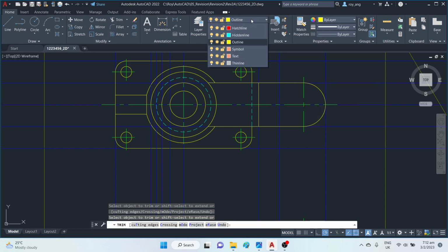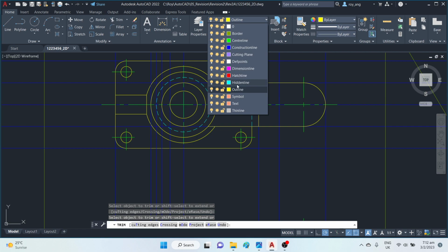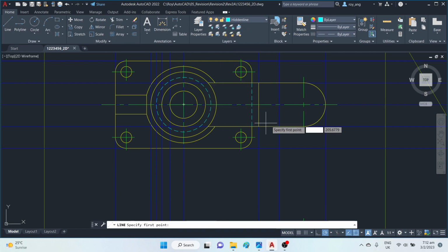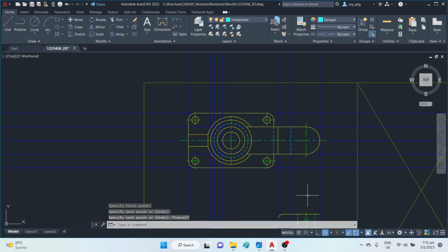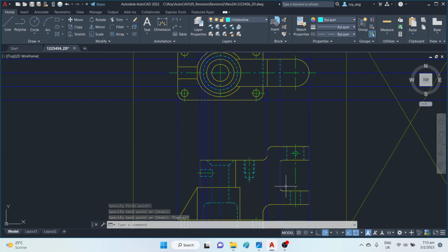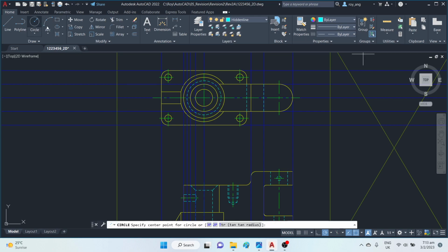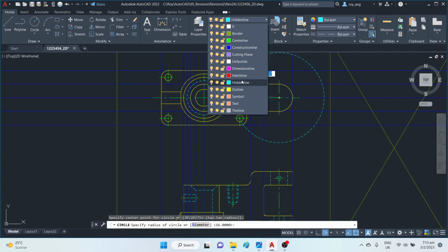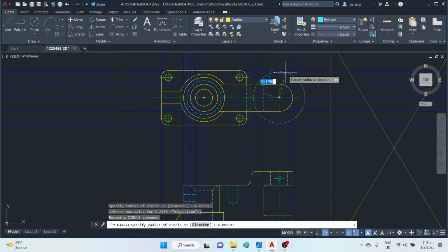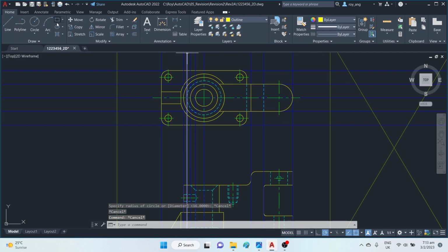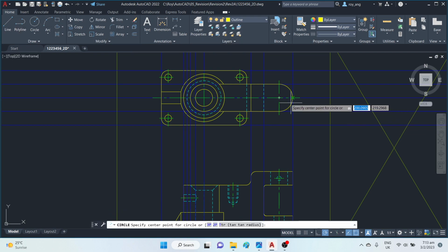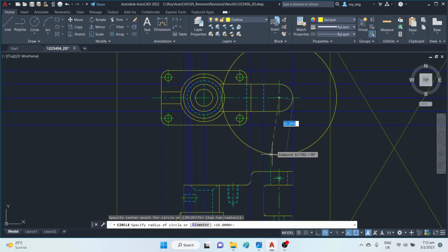Going over here, the next one, as I progress towards the right, the features that I'm drawing out, and this is the hidden line. Right, this is a hidden line because if you were to go down, you will not be able to see this edge. Okay, then you would go and draw the circle, the outline, draw the circle, and what I can do is I can make use of this.